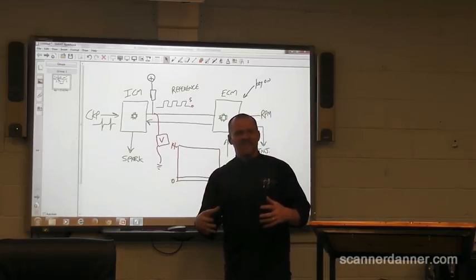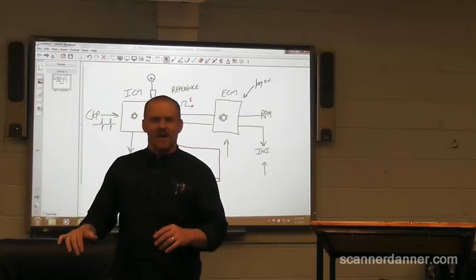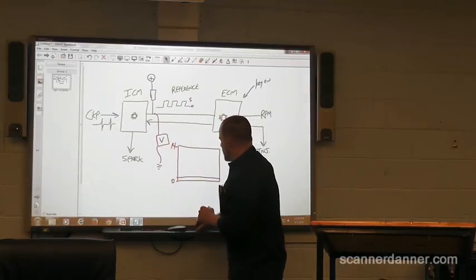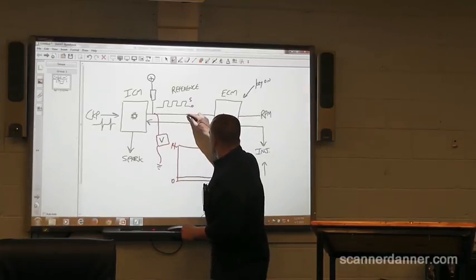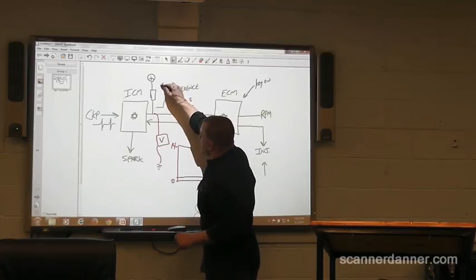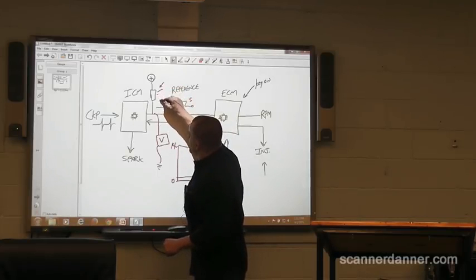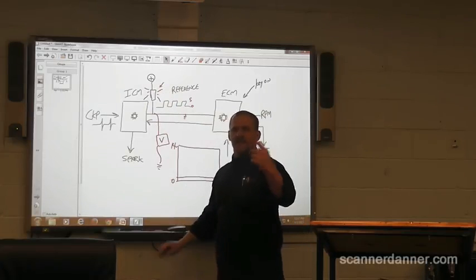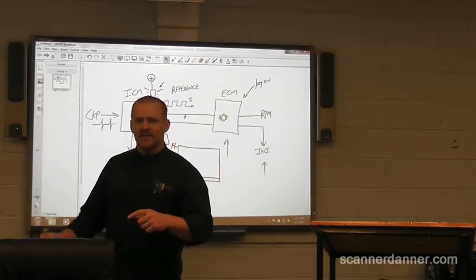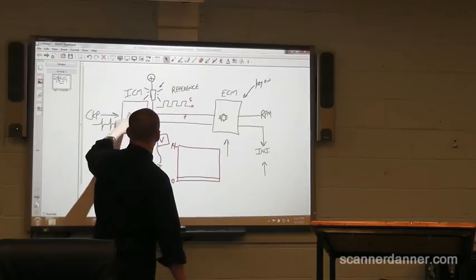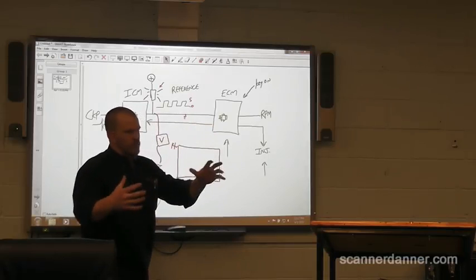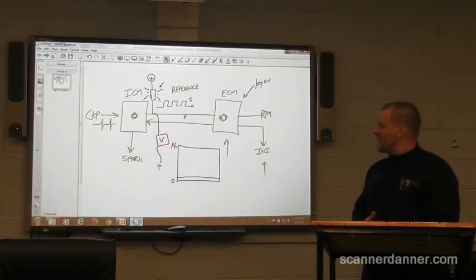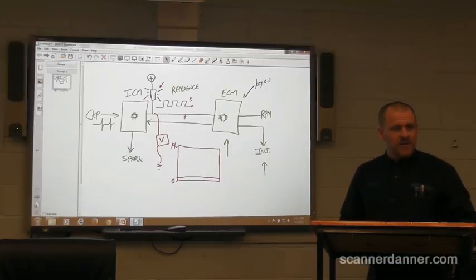There is a point of this story where we're on short to ground testing. I thought of a short to ground, but I thought that if my wire was shorted to ground, let's draw a short in here. If this wire was touching ground, when I did this test, my test light would have lit when I connected it. And that's the part of this troubleshooting procedure: if the test light lights, the wire is shorted to ground. These circuits that you're creating, these signals, are really between some chips here. They don't support current flow that test light would carry. And the test light did not light. So I said, that wire's not shorted to ground. Made the call, but where's my signal?